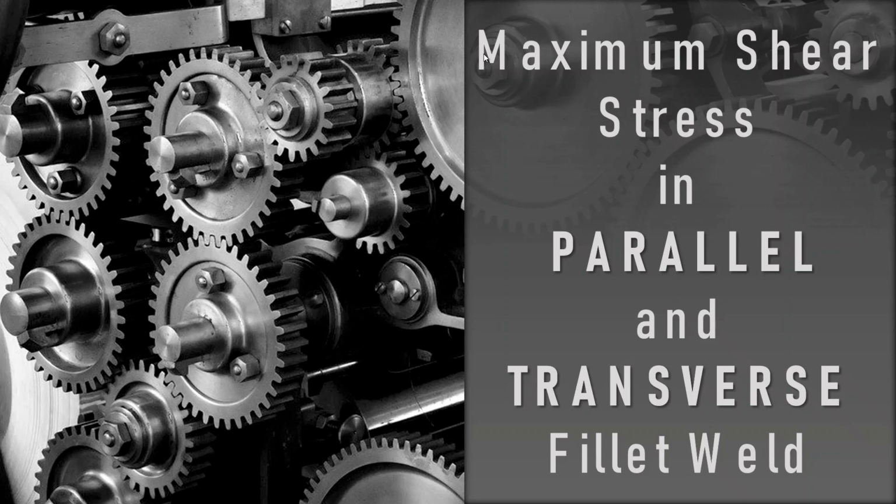You can see that this lecture is on maximum shear stress for parallel and transverse fillet weld. In this lecture, I'll explain to you how to find the inclination of the plane inside the weld where the maximum shear stress is induced and the magnitude of the induced shear stresses. This will be done for both types of fillet weld, that is for parallel as well as for transverse fillet weld. By the end of this lecture, you will see that the plane where the maximum shear stress is induced is inclined at an angle of 45 degrees and 67.5 degrees respectively for parallel and transverse fillet weld with respect to the horizontal plane or the leg dimension.